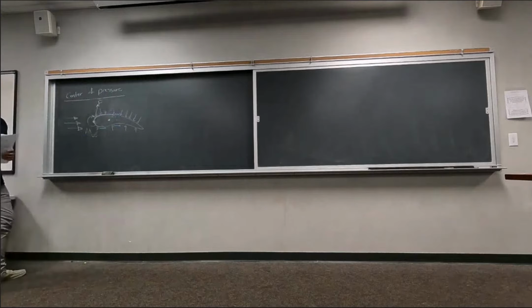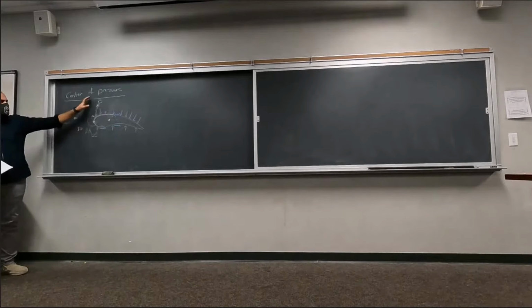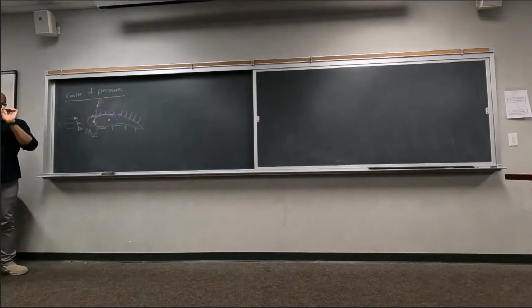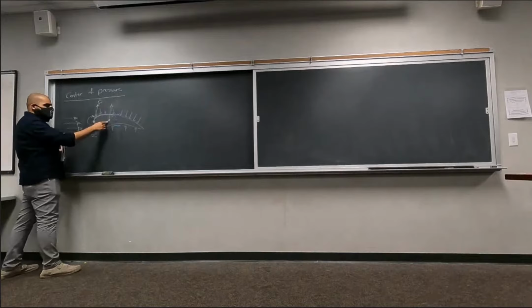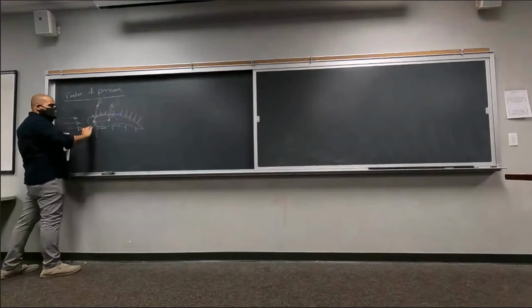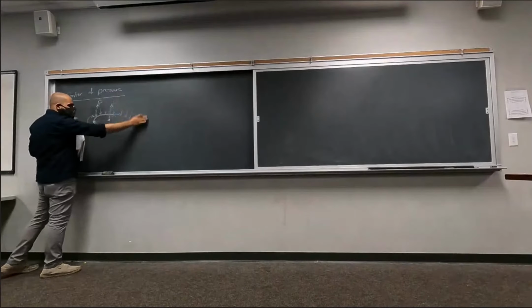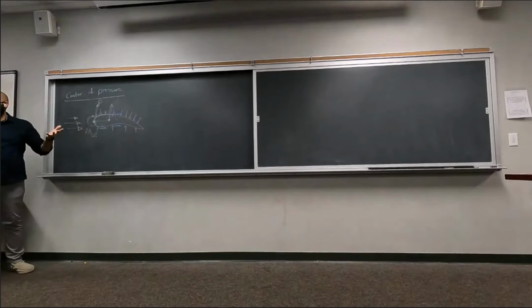We are looking for a point inside this body or outside of it, right? At which we can represent this resultant force and moment with only one force. What does it mean? It means that whatever moment the force at this point applies to the leading edge must cancel the total moment that is being applied by all of these forces at any point, essentially. Okay?